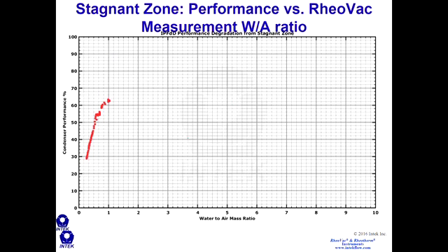And so if you were to plot condenser performance or cleanliness factor versus water-to-air mass ratio, which we did for this unit, you get this relationship here. And this occurs for every condenser out there. You can create this characteristic curve and know exactly how much performance is lost due to air and leakage in the condenser.